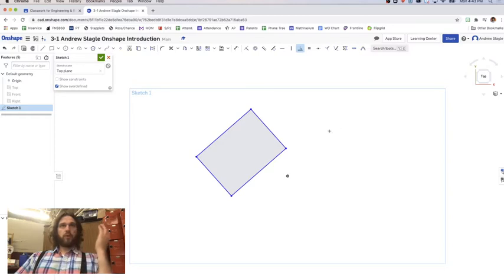So now, by default, since this is a right angle, this is a right angle, and this is a right angle, the last one has to be a right angle. And when you select that, it's like, okay, great, that's just fine. So we have just forced this quadrilateral to be a rectangle. Now, if you come over here and select Show Constraints, it shows that, hey, these lines are perpendicular. And it says these lines have to be, I think that's the coincident constraint there.